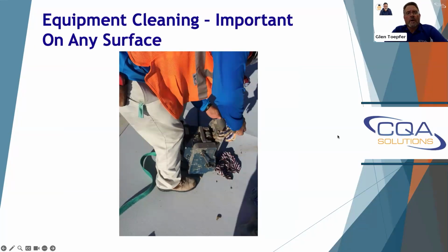And I think the thickness overall gets into one of the issues with what you see going through the intersections. People will weld through the intersections, and there's two schools of thought. In Europe, I guess it's a pretty standard practice. It is here in the United States. Everybody likes to weld through the intersections, grind them down, weld through them, and do a long continuous air test. But one of the people that used to work for the manufacturers back in the day told me that he thinks it's a bad practice because in his experience, machines loosen up internally.